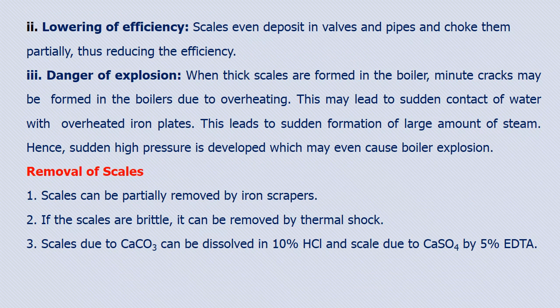Second one, lowering of efficiency of the boiler. Just like sludge, scale also deposits on the walls and pipelines and chokes them partially, thus reducing the efficiency of the boiler. Last, a very important point, danger of explosion of the boilers.